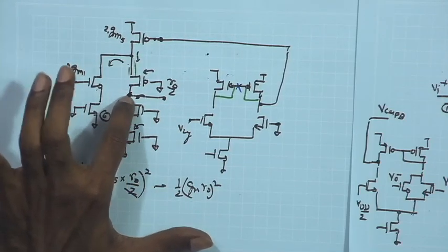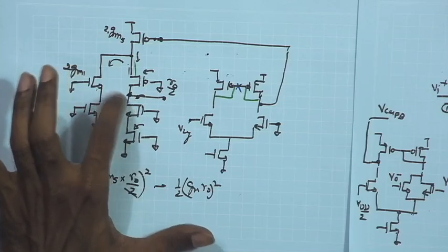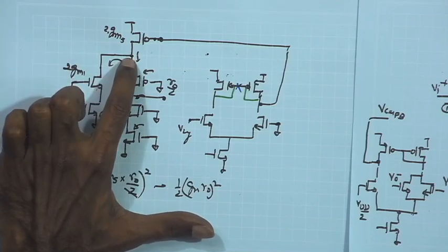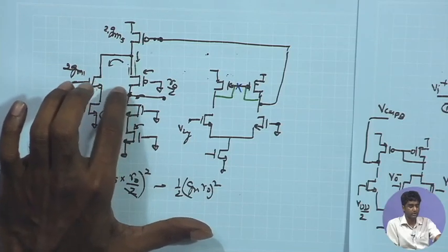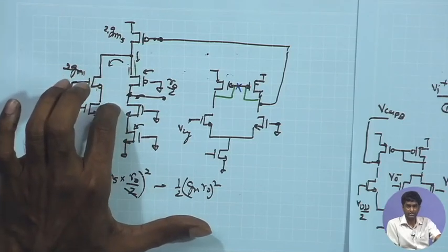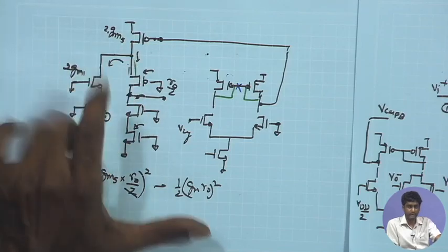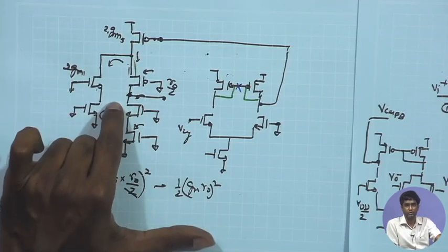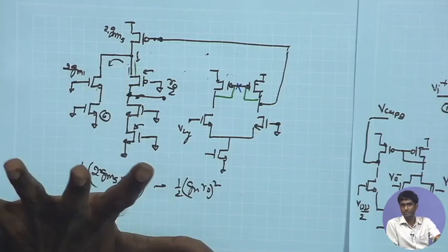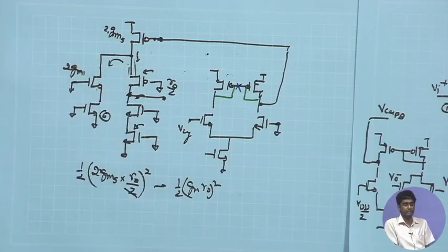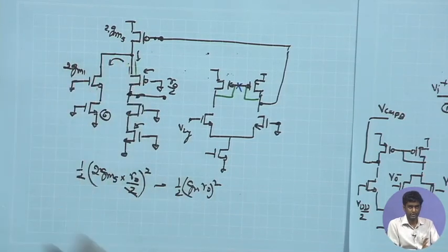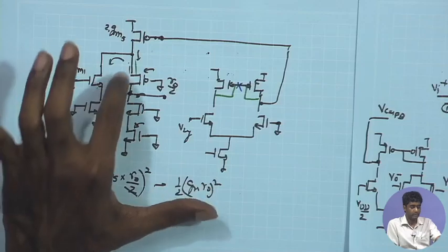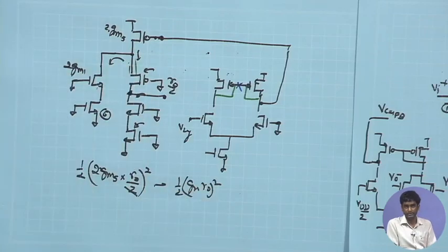And here we have the impedance, which is gm ro times the impedance at this point, and hence the other option left is that you make the capacitance gm ro times larger at this point as compared to this point. The target is to make the capacitance over here gm ro times larger as compared to the capacitance at this point. That is what we discussed yesterday while discussing the stability. And in that case, if my gm ro is expected to be around 100, I would like this capacitance to be 100 times larger than this.